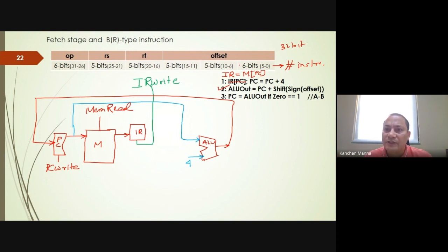Now, the memory that we have here is byte addressable memory. In that way, each instruction will take 4 consecutive locations to store it. Because of that, after performing the sign extension of the offset, we have to multiply that value by 4. Why 4? Because each instruction takes 4 consecutive bytes to store in the memory. So now, let's say we have a sign extension unit here.